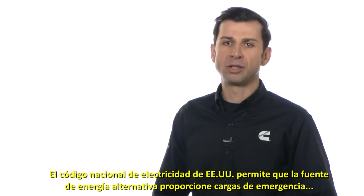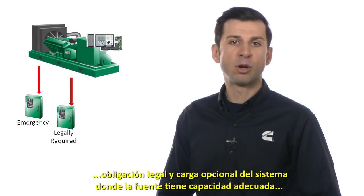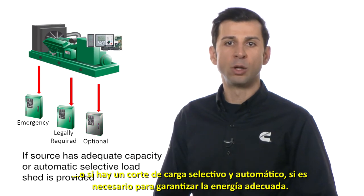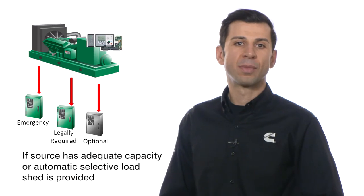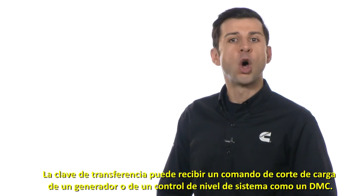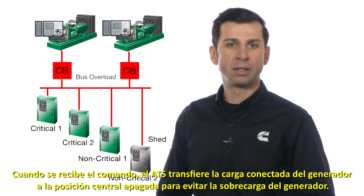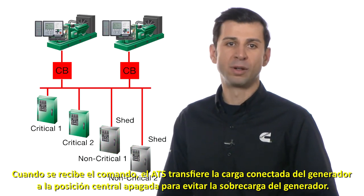The U.S. National Electric Code allows the alternate power source to supply emergency, legally required, and optional system loads where the source has adequate capacity or where the automatic selective load shed is provided as needed to ensure adequate power. The transfer switch can receive a load shed command from a generator or a system-level control such as a DMC. When the command is received, the ATS transfers the connected load from the generator to the center off position to prevent the generator from becoming overloaded.